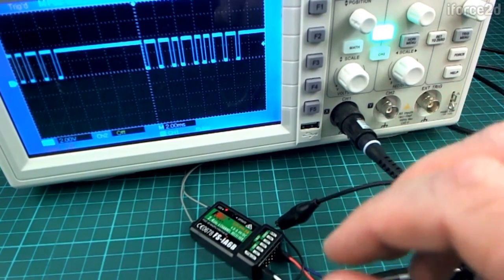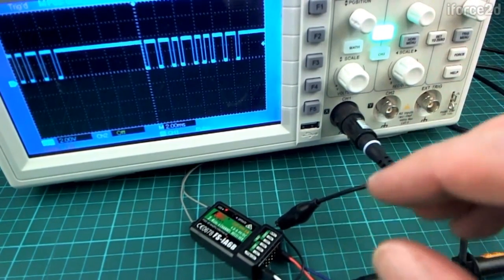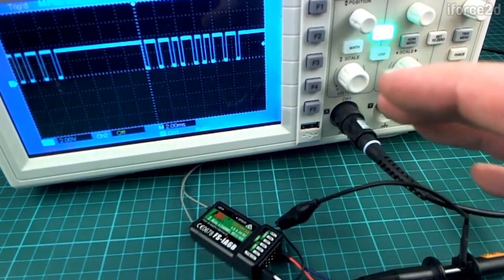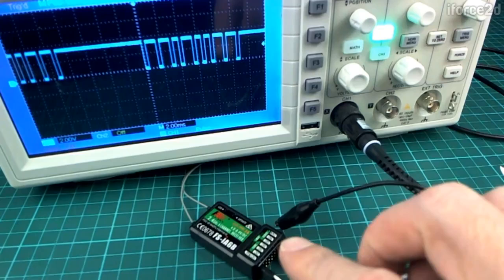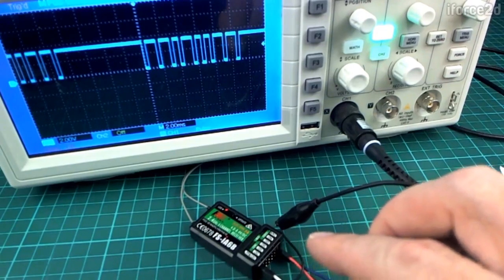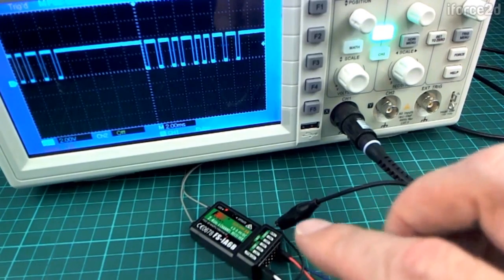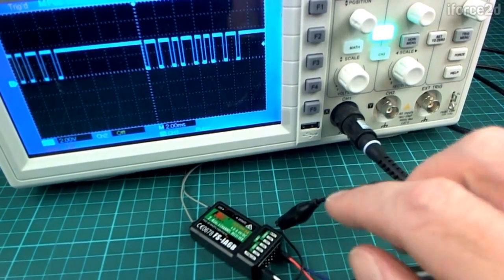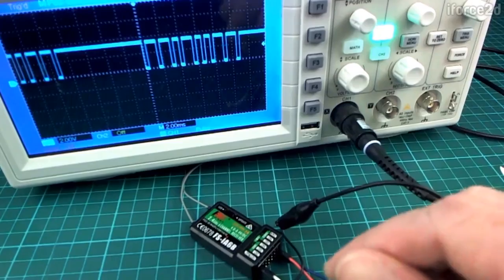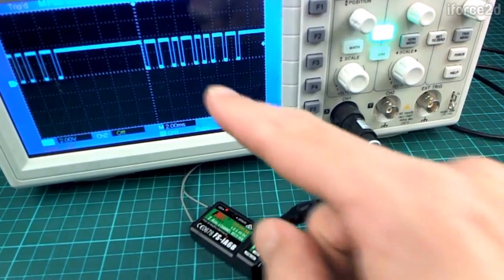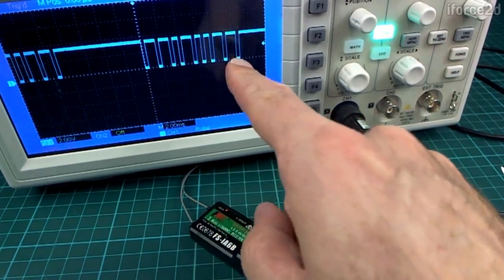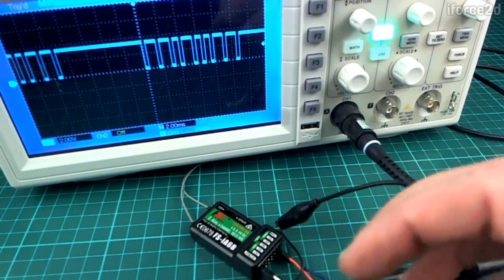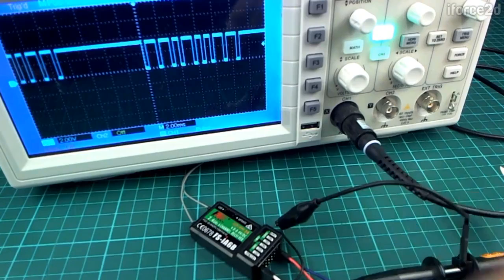In fact, I almost didn't do this part, and you really don't need to know how the details of this all fit together. But suffice to say that iBus is what's known as a serial connection, and it allows you to communicate information faster from the receiver to the flight controller, and it also is able to handle much more sophisticated information, so not just simply the positions of the channels like we have with PPM here. You can also send a variety of other information through this type of connection as well.